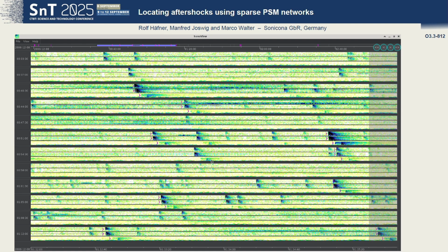3 is regarded as the absolute minimum seismic network that you can use, but we can do better. This is data from monitoring of a geothermal borehole. There were some injections, and what we see here is an event cloud. You see these triangular blue plots are the signatures of small seismic cracks. If I had a laser pointer, I could show you the very smallest ones. While dark ones are obvious, you always have this triangular shape that you can use to identify seismic signals.